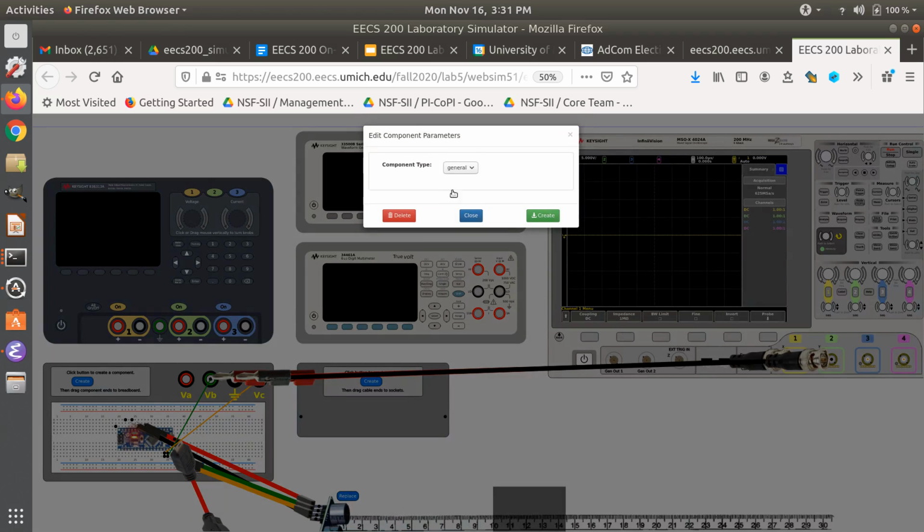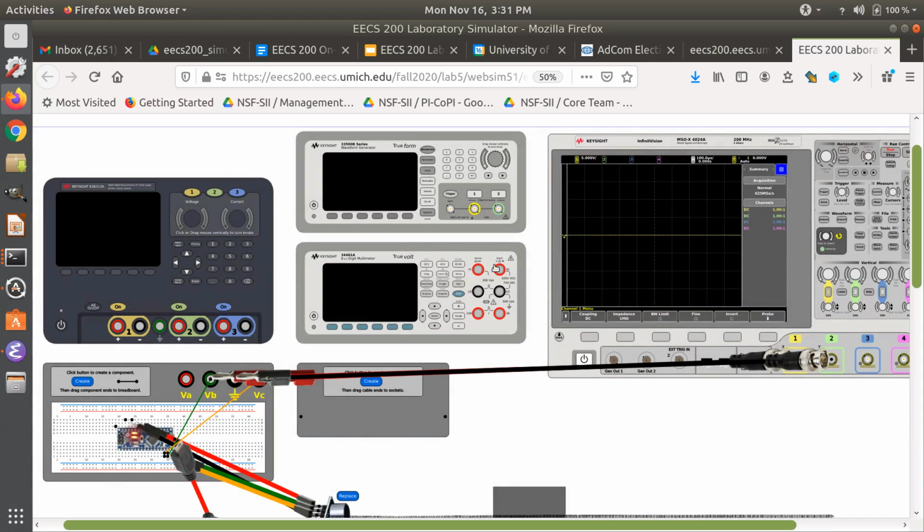If it's not connected right, then it doesn't show what you would expect. And it basically shows nothing in this case because we don't have ground connected. So we need to connect ground. So this end should go to ground, and I'm sorry, all these things are piling up on top of each other. You just kind of have to know that it's right there. And then this other end goes to the ground on the Arduino.